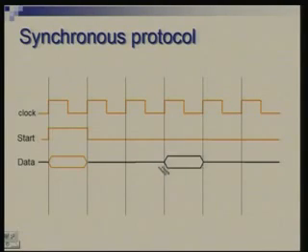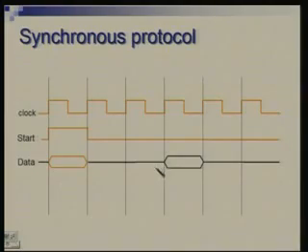a fixed number of cycles. So in this case we are assuming that with a gap of 2 clock cycles the data will be available. So the device can make this assumption that once address has been given, without waiting to check whether memory has seen the address or not, no confirmation is sought, and you simply wait for 2 clock cycles and then pick up data from the bus.